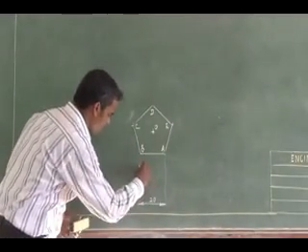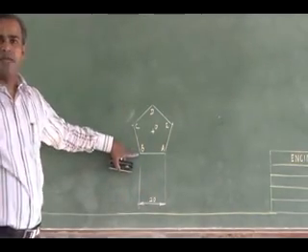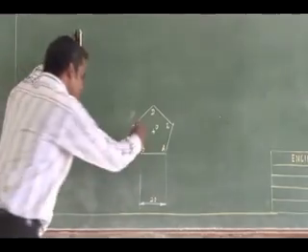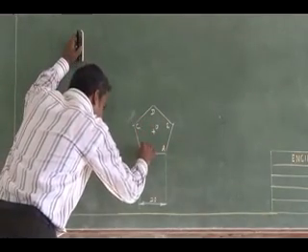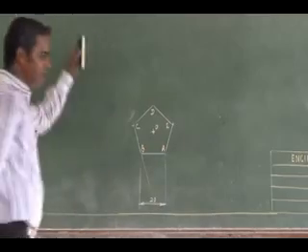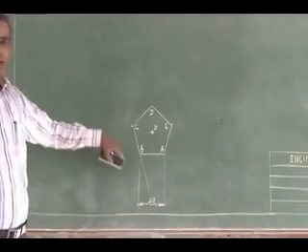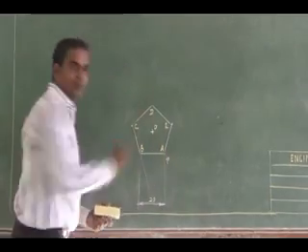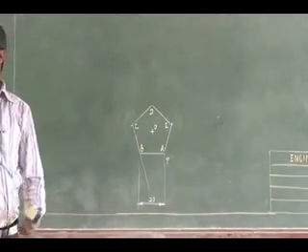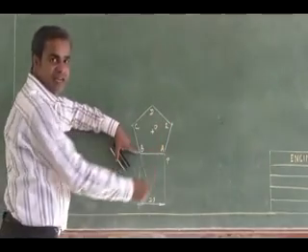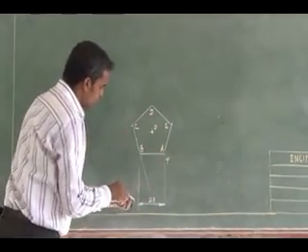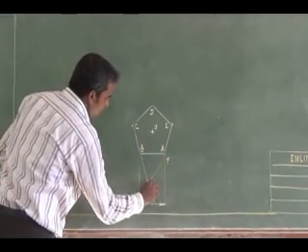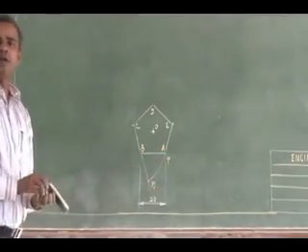See here, BC. I have to extend CB in the negative direction. See here, CB, tangentially, I am extending like this. Now I have to keep my B. The A is nothing but my point B. Keeping B as center, BA as radius, I can draw a curve using compass. This is my B1.